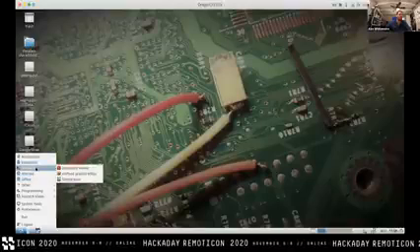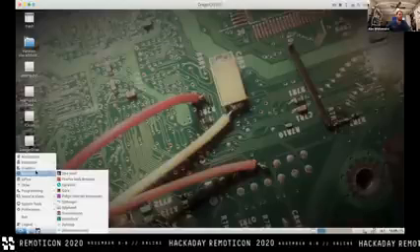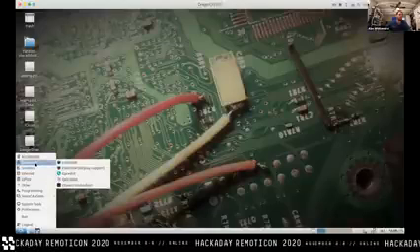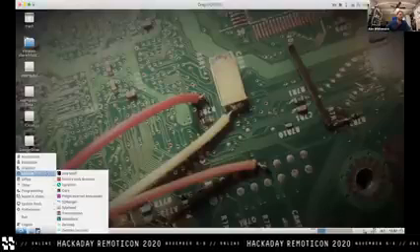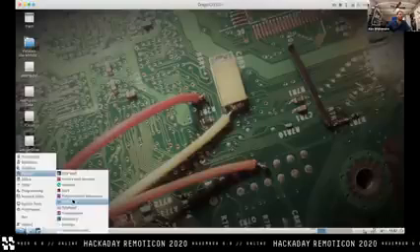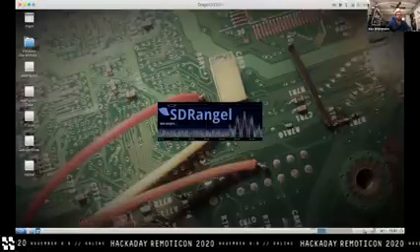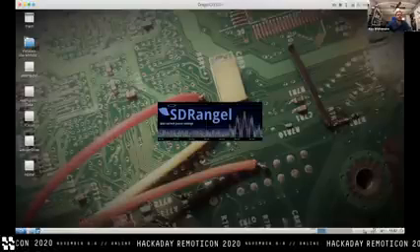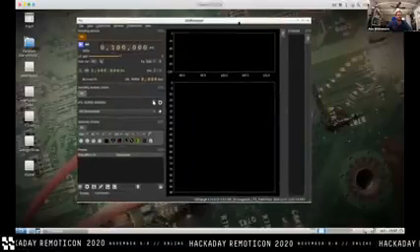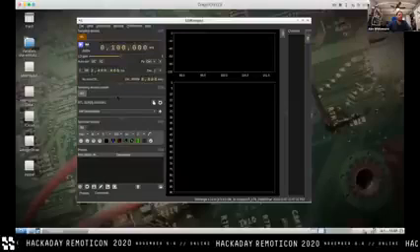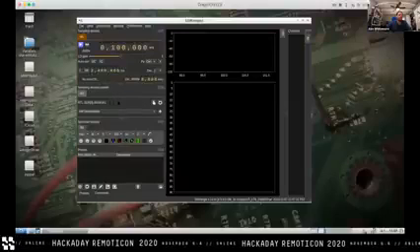Okay, so first things first, we're going to fire up, I guess let's start with Q Spectrum Analyzer. No. I'm going to fire up SDRangel. It's under the Internet menu down here. We'll load this. If you're using a different version of SDRangel, I think this interface actually changed slightly. So down here under Sampling Devices Control, RTL SDR is automatically selected for me.